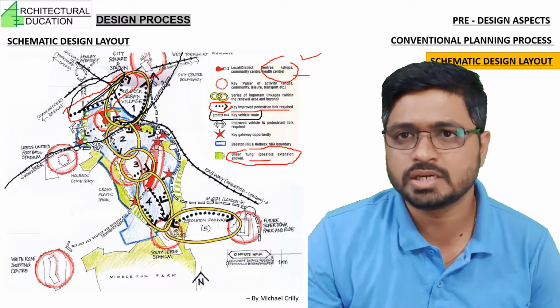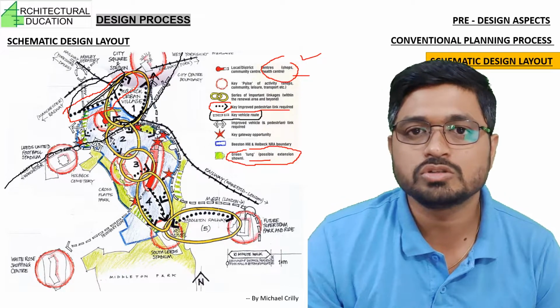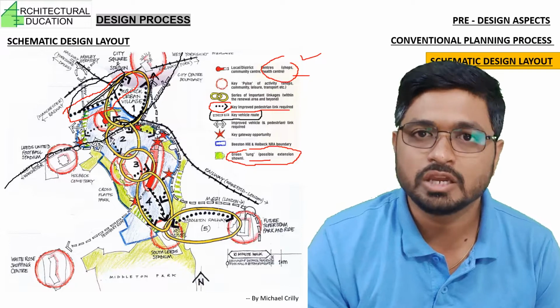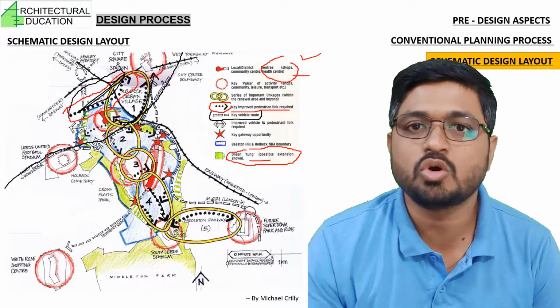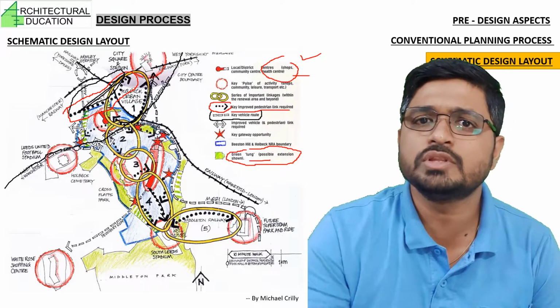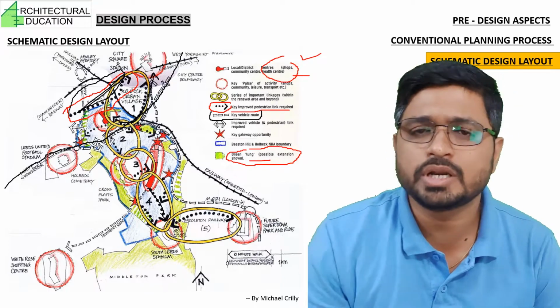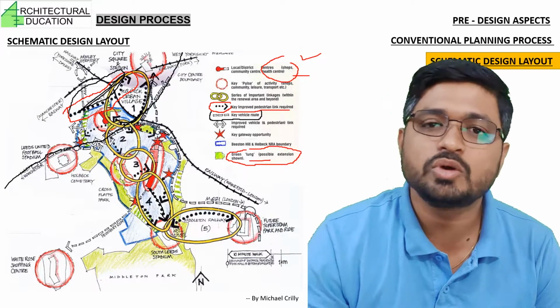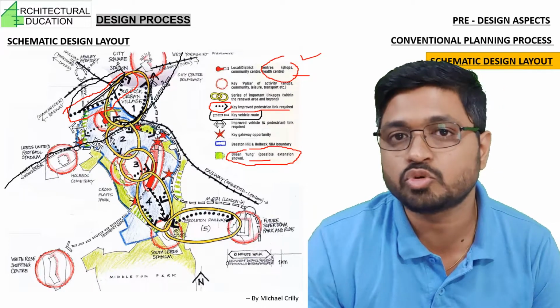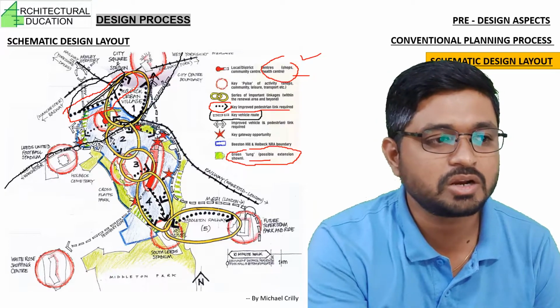For example, if you are designing a resort, you can also place certain elements like information kiosk location or restaurant location, cottages location, and then you can show it with the vehicular movement and pedestrian movement, how they are being tracked. Put an arrow mark, give a shape to that building, try to connect it to the area statement and give a proportionate space over there in this kind of plan